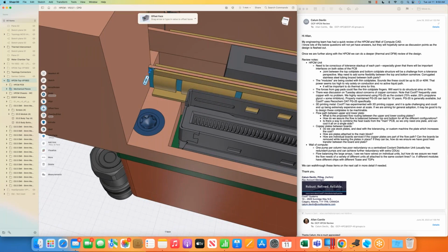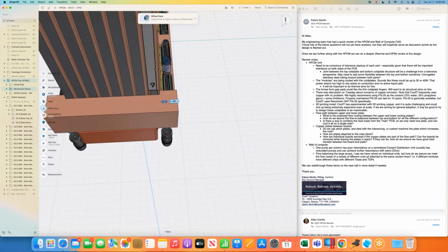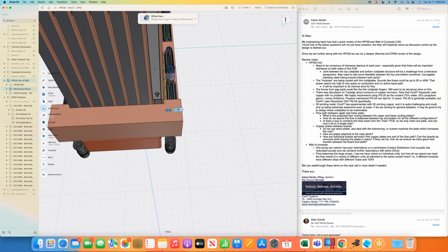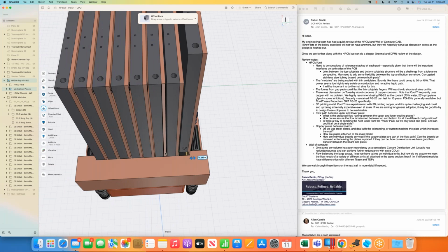So as well as extending the width of the module from 7.5 to 8.5 millimeters, I think we need to increase the spacing from 9.3 millimeters to 10.3 millimeters, if that answers your question. Yes. Okay. Thank you. But at the moment, it's 9.3. It is fully compliant with EDSFF right now, but I was going to extend it to 10.3.